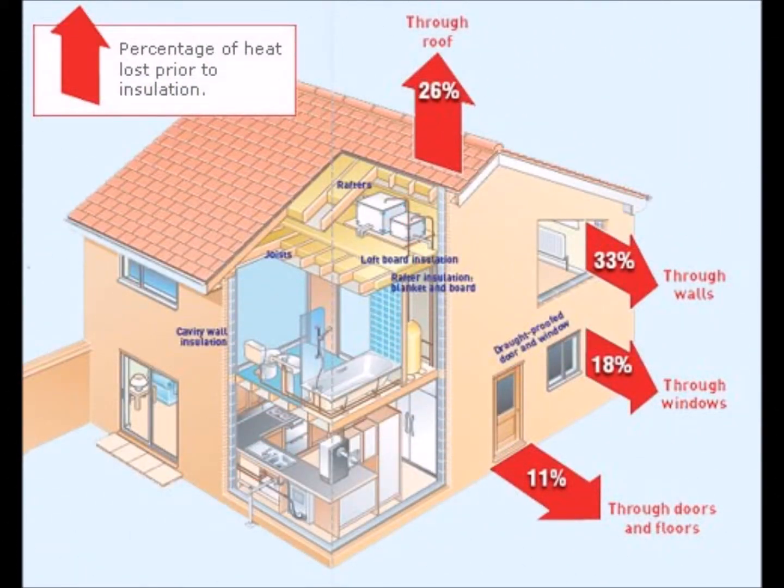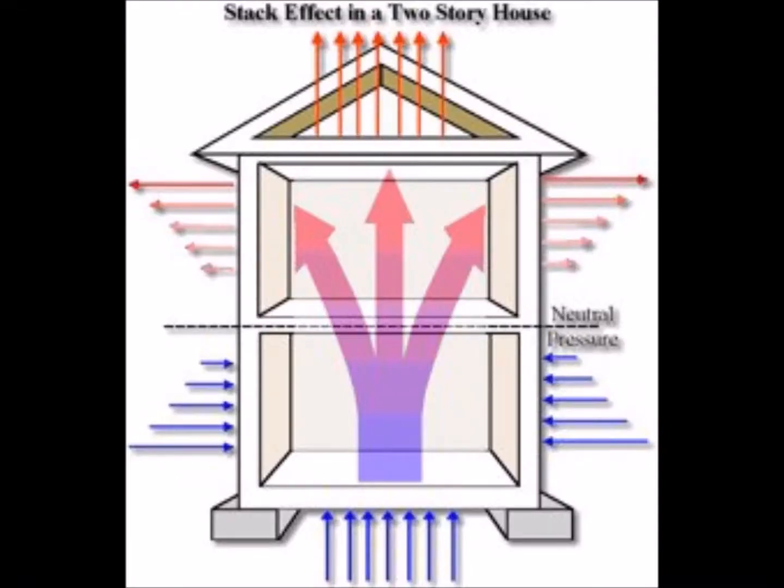the top plate at a partition wall, the entrance to an attic space, around interior trim, any of the registers of the furnace, holes in plaster or drywall areas, built-in dressers, cabinets, and shelving, anywhere around laundry chutes and floorboards, knee wall and framing intersections. Also air leakage points between the crawl space and conditioned spaces, around dormers and additions, overhangs, electrical wall receptacles and outlets, porch and house framing intersections, just to name a few.